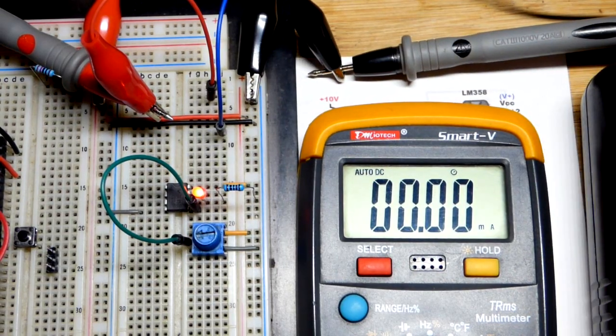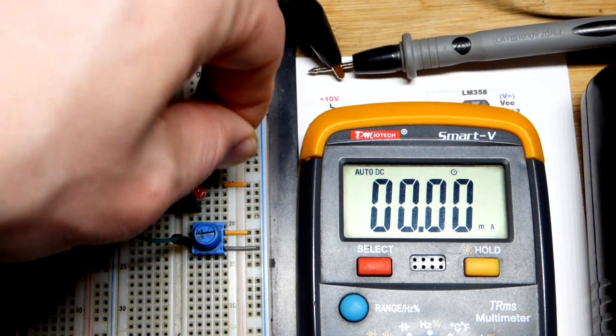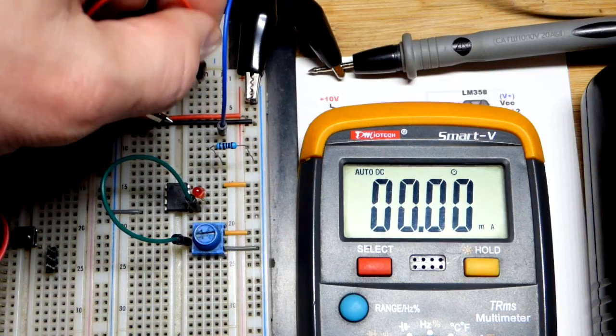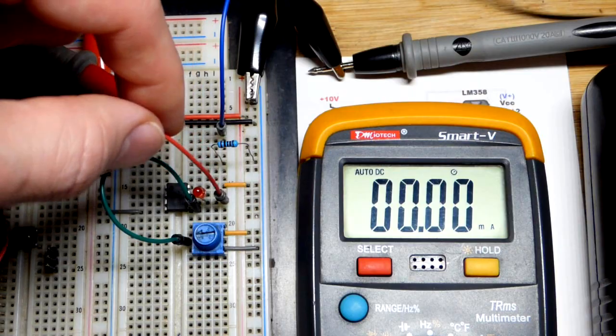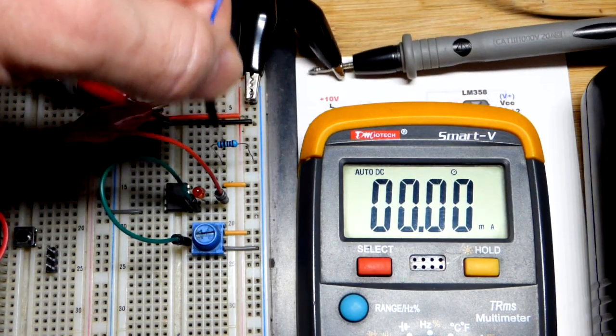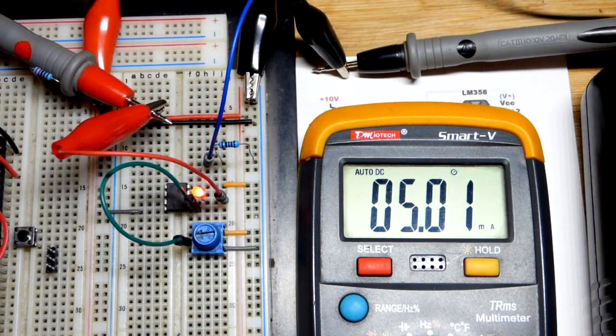But in any case, one important thing we got to do is open the circuit where we're going to measure it. So I'm going to take the 1K resistor, move it up there. Of course, now no current is flowing, and the LED is off. And we're going to be careful, make sure I go to the right spot. So we're going to the inverting input right there, and now we can go to the resistor. So we're bridging the gap. The current has to go through the meter in order to read the current. And there you can see it is pretty close to spot on 5 milliamps of current.